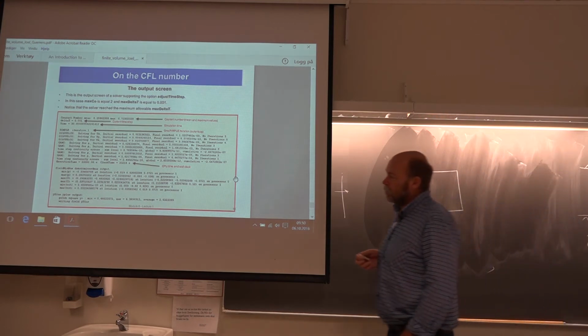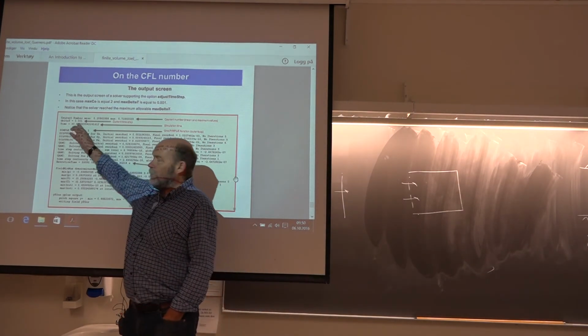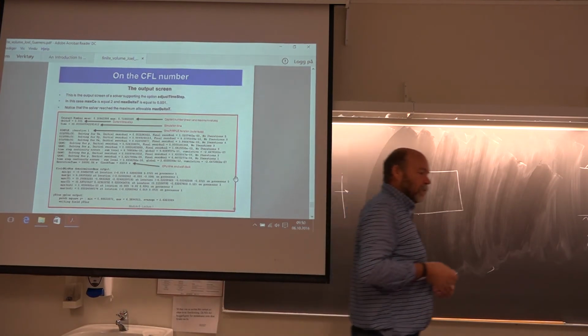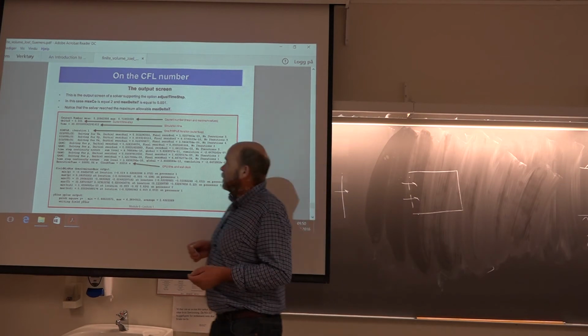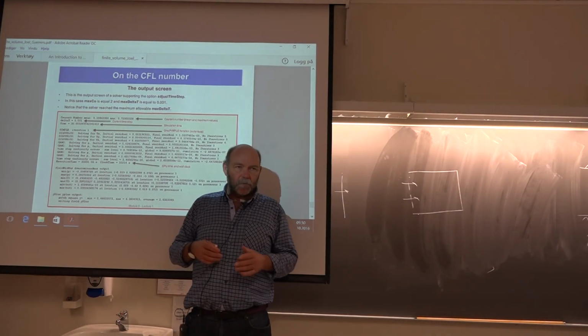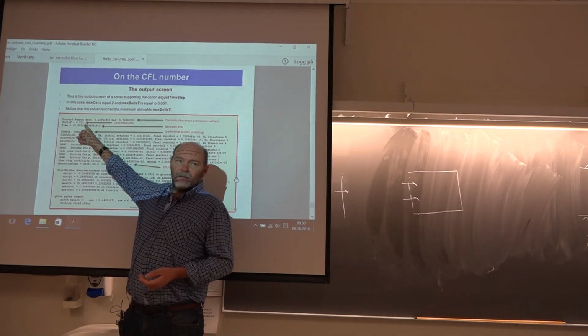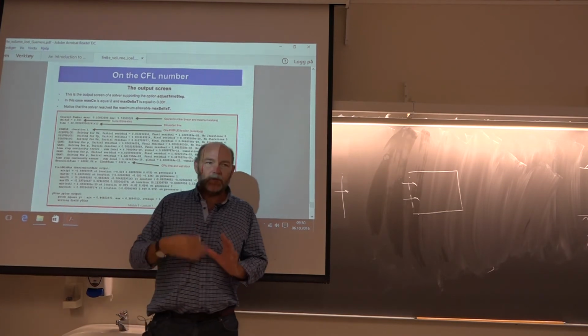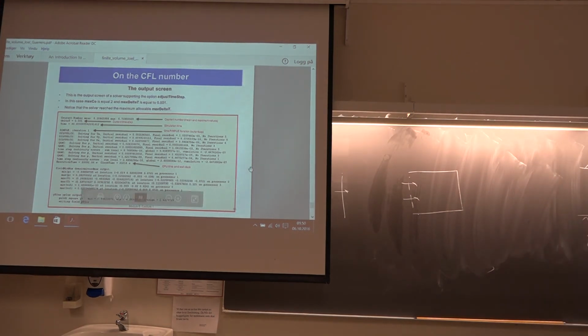But if I had programmed it or chosen a system where it automatically should adjust the time steps so it still should be stable, then actually it will try. But then you risk wasting a lot of CPU time sitting there watching your computer simulating, with a time step of 10 to the minus 10 or something in seconds. So it's going to take forever to obtain a solution, and in the end it will fail anyway. So if you're using these automatic time adjustments, be aware. You should have a peek at it.